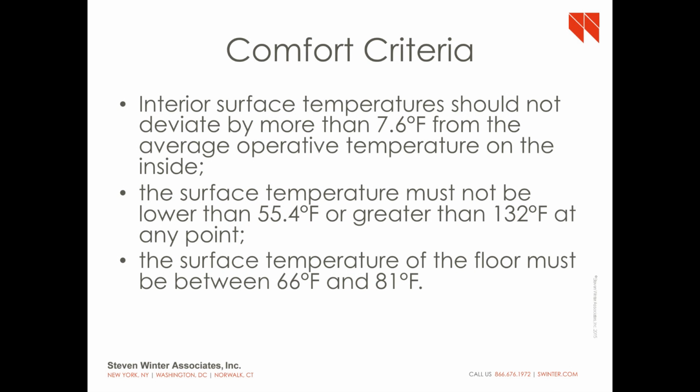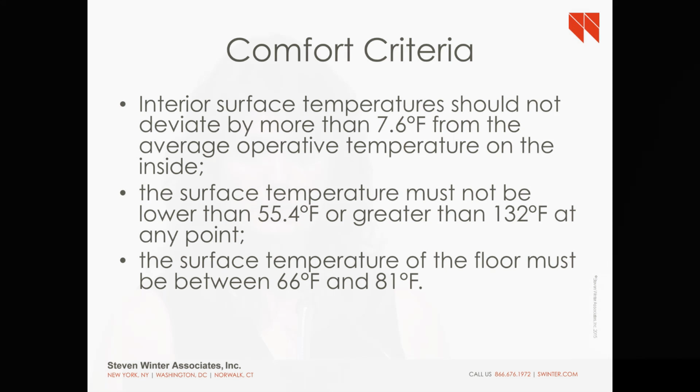So I think I just covered this. This is what the 3 criteria are for the comfort criteria. They don't want you to deviate more than about 7.5 degrees from the average operative temperature. I think it's a little higher than that, actually, but that's about average. And then the surface temperature should not be lower than 55 degrees or greater than 132 degrees.